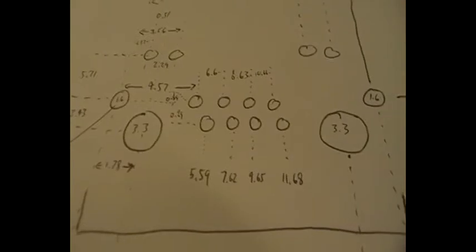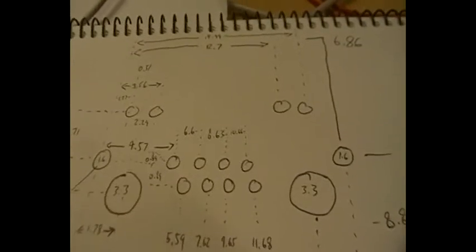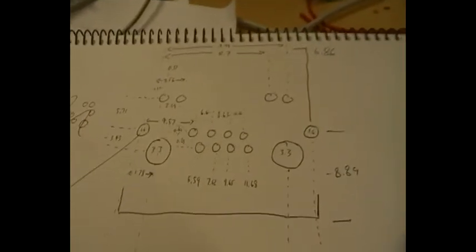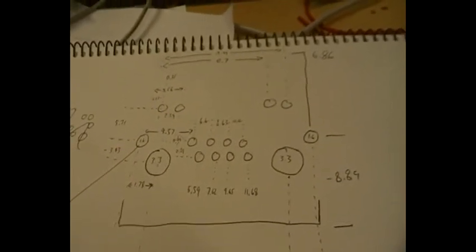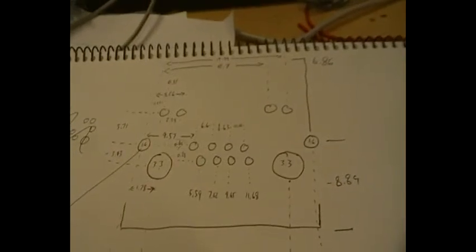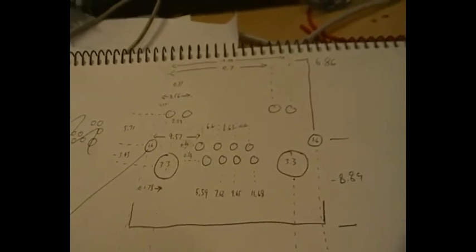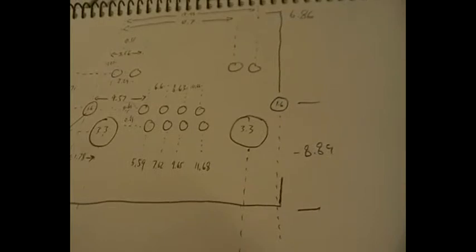But you can see, even for those pads, even though they're on a grid, I prefer to sketch this out and put the X and Y coordinates of the individual pads in it. I sometimes do that even for big QFPs. I'll write down all the X and Y coordinates of the pads, and I'll just place them at those coordinates once I've figured out where they all go. Actually, QFP's probably a better example of somewhere where you can change the grid or use the auxiliary origin. But for a component like this, where the pads are here, there and everywhere, I definitely prefer to do it this way. So that's what I end up doing.